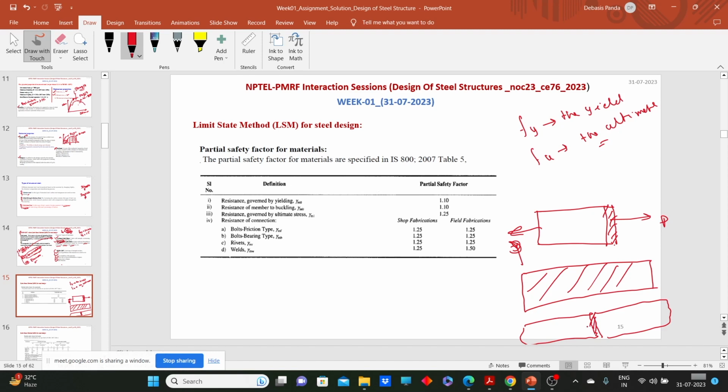Sometimes it will crack and break apart. So now we understand we need to consider the serviceability limit state and ultimate limit state. If there are excessive elongations, this stage we also call a failure. For a solid plate, the tendency of rupture is a less likely phenomenon.